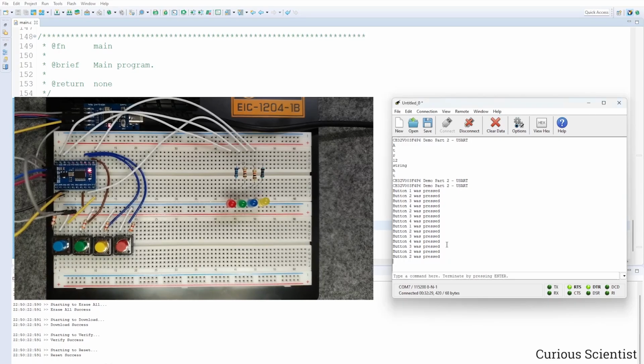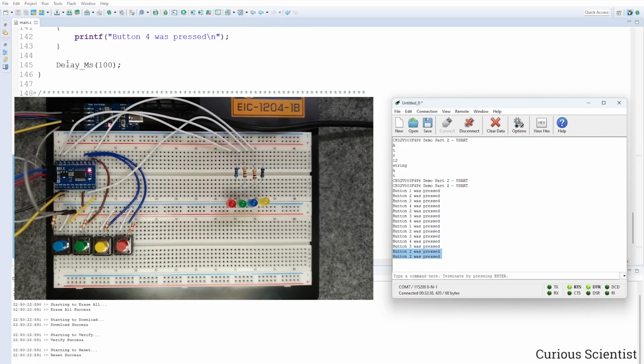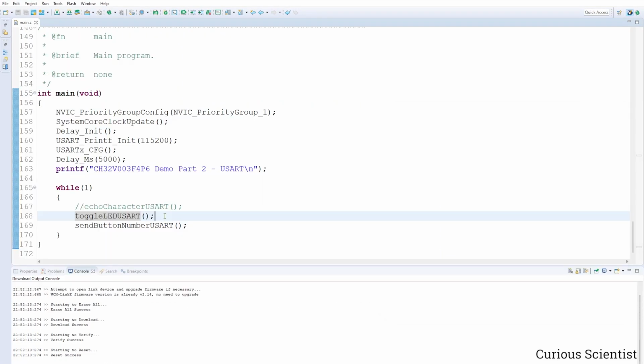Here actually you could see a bounce because the same number was printed twice. So the delay, that 100 milliseconds delay up here, was not enough. So maybe we can put there 200 milliseconds or even more if it's not time critical code. But yeah, it works. So now we can toggle an LED or multiple LEDs and also receive, let's say, information from the GPIO ports.